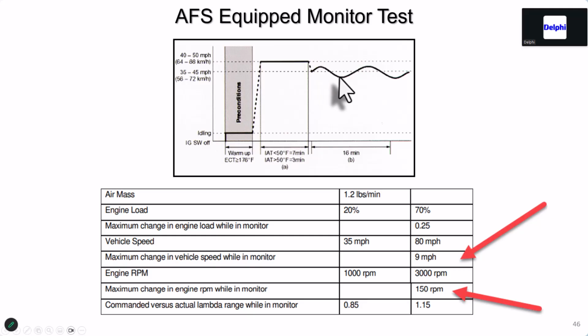You can get this done in a matter of minutes using that technique and be back to the shop before you even knew it. Just be careful when you're doing this on the freeway that somebody's not on your rear bumper. But generally 35 to 45 or 40 to 50, that's the window. Just variation, light up and down, trying to enrich it, lean it, but without overdoing it.